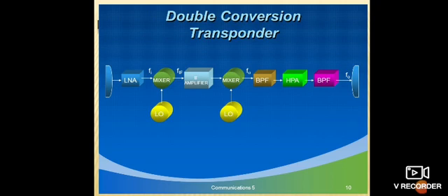And the HPA is used for high power amplification. That means, in order to increase the power level of the downlink signals, it increases the signal level, and this is given to the BPF, that is the band pass filter, for eliminating some more harmonics which are present in our downlink signals. Okay, then it is given to the transmitting antenna. This will send the signal on its way over the downlink.